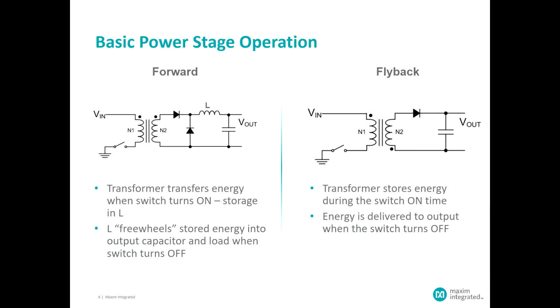So while the schematic for these two transformers looks the same, they are significantly different in their performance. The flyback circuit has energy storage capability. It's characterized by the inductance of the primary circuit, and its purpose is to store energy in that inductance. The circuit on the left, which is the forward, is supposed to just transfer energy.